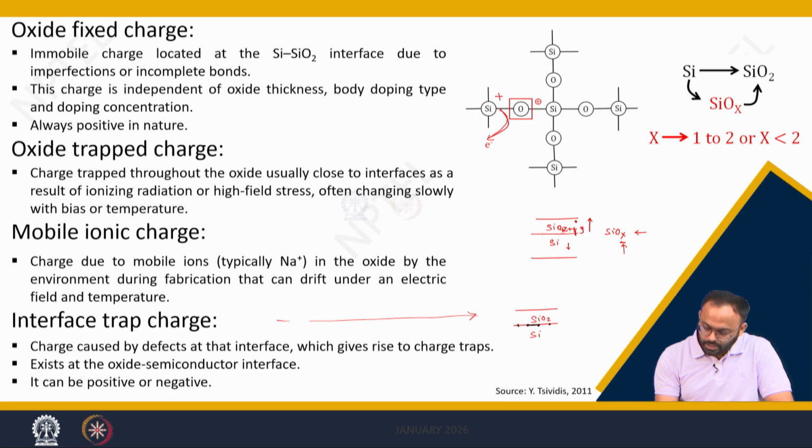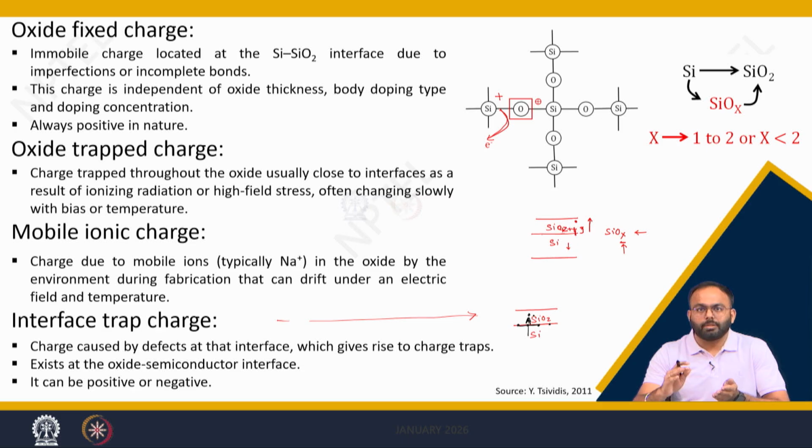Let us consider this is a silicon atom which is of our interest, and this is A, making a covalent bond with the neighboring atom, one like this. But what will happen to the top of the silicon atom? When you dice the wafer, some of the silicon atoms will get cut off. That is called dangling bonds.